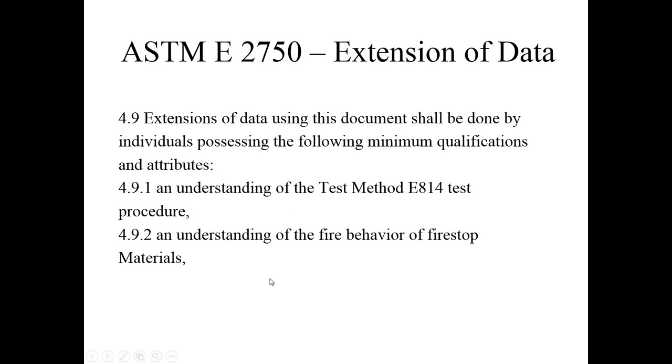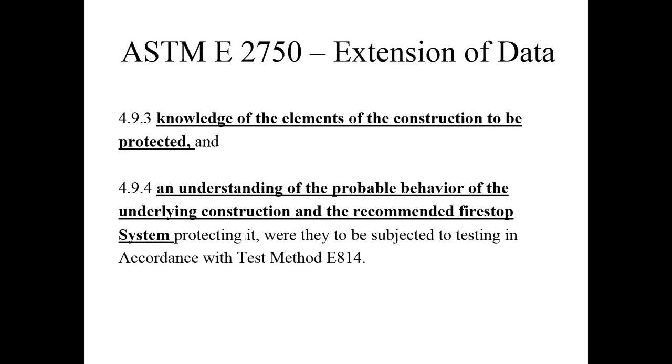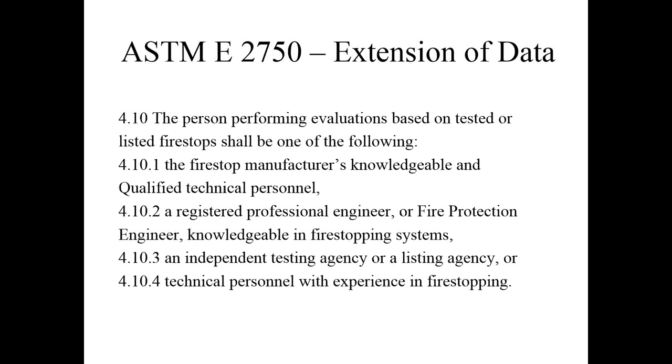So whoever uses this has to have an understanding of E814 and the fire behavior of the firestop materials. The only way you can have the understanding of the fire behavior of the firestop materials is if you stand there while the fire test is going on to know what it does. And then knowledge of the elements of construction, and understanding of the probable behavior of the underlying construction and the recommended firestop system protecting it. Pretty important stuff.